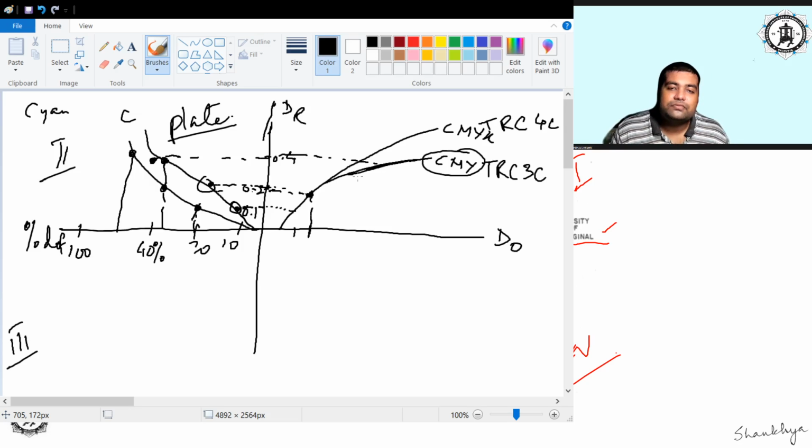All right. I have obtained what type of dot percentage I need to reproduce in my plate, but what I have not done is find the type of dot percentage I need to reproduce in my film to achieve this particular tone reproduction curve after printing. So let us see how it is done. For example, let this point be 0.2 density, let this point be 0.4 density, whatever.